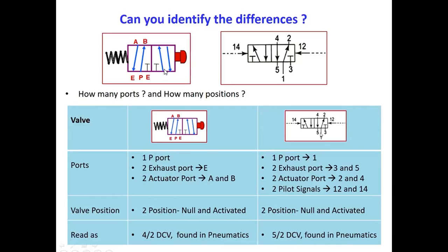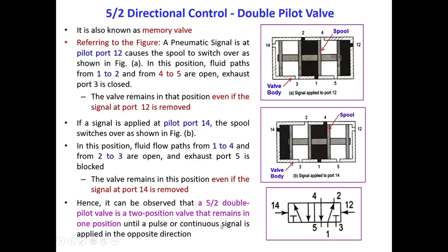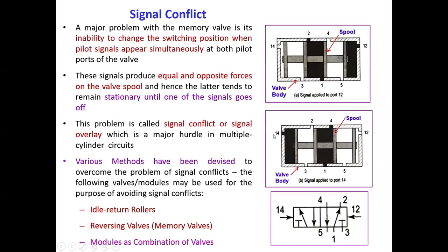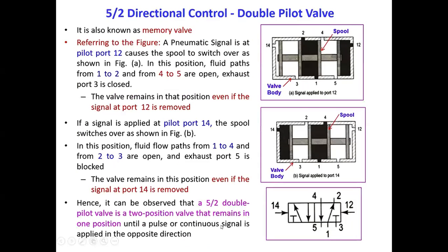This is 4/2, but this is 5/2 because of 2 pilot signals, 12 and 14. 5/2 DCV, direction control valve, double pilot valve. It is known as a memory valve. Referring to the figure.